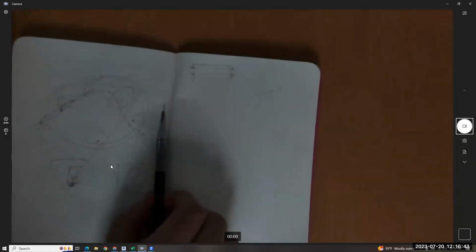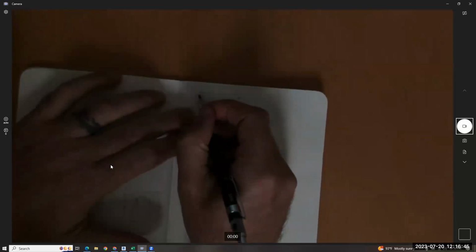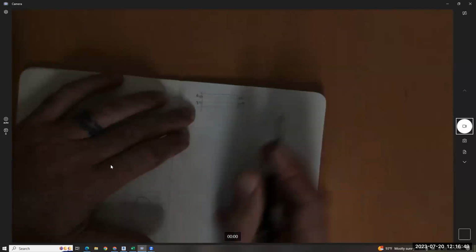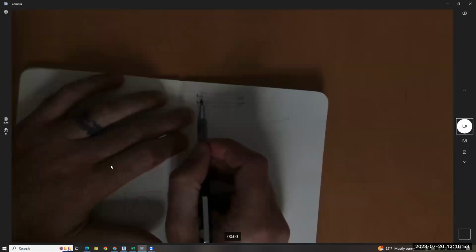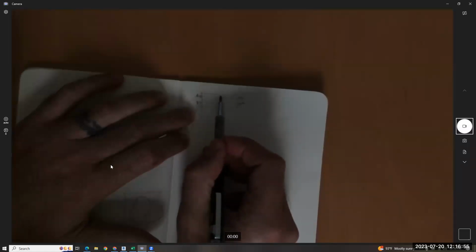That's one thing. So we could just calculate trib area, right? So let's say if we labeled column A, B, C, D, we could say trib area for A is half the distance here and half the distance here, right?